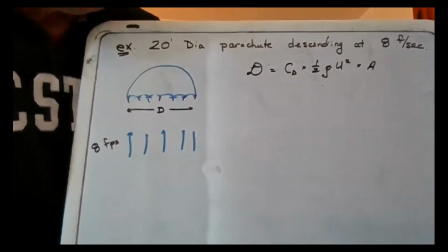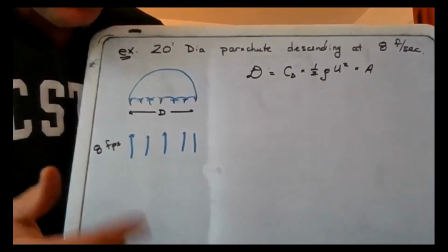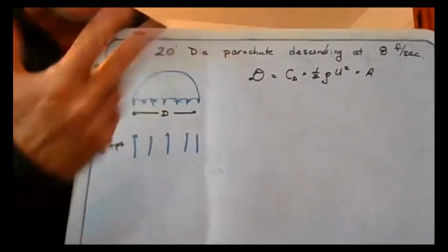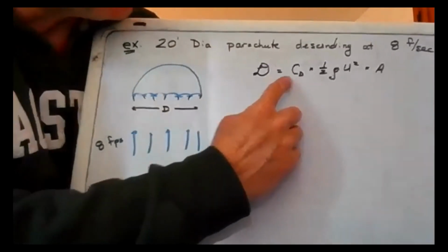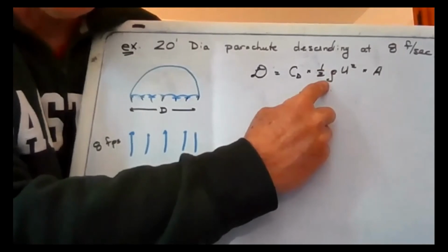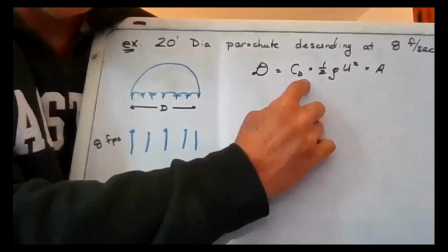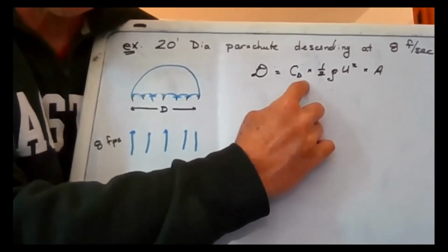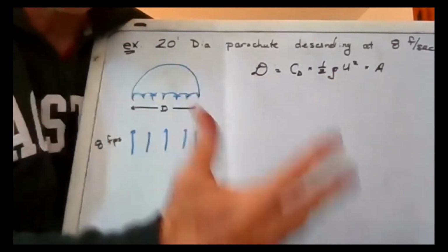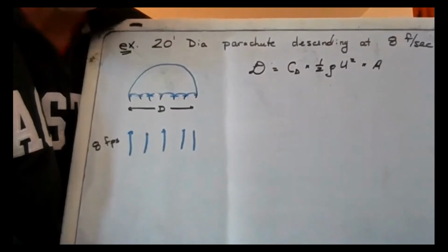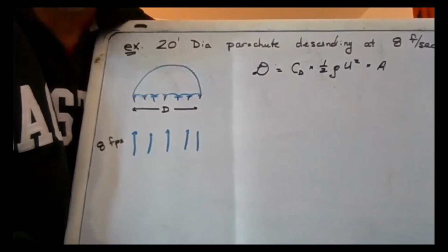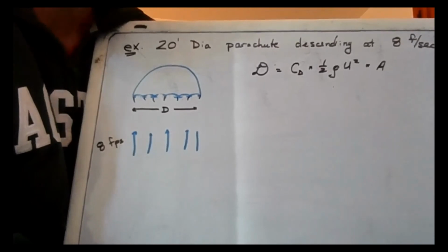Okay, good. By the way, it can be in the same direction as the motion of the fluid or opposite the direction of the motion of the object. So that's the drag. So we need to go through and do this calculation. 1/2 rho u squared is not going to be that difficult. C_D, we've got to find an appropriate source within chapter 9. And then area, hopefully if we read carefully, it will tell us what area to use. So for starters, let's take a look at figure 9.4 and see if that's going to do the job for us.